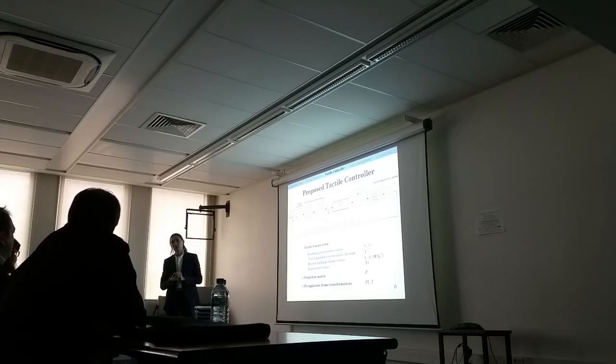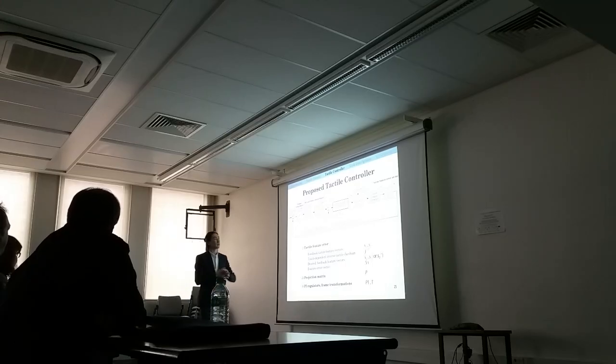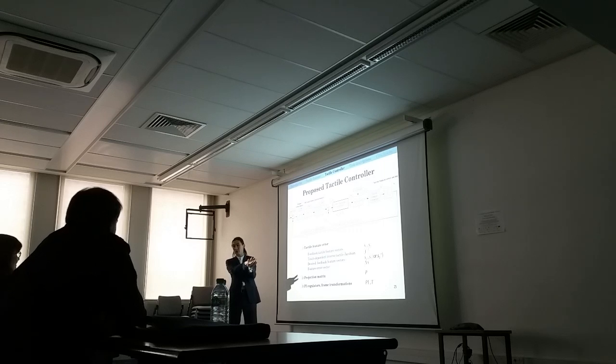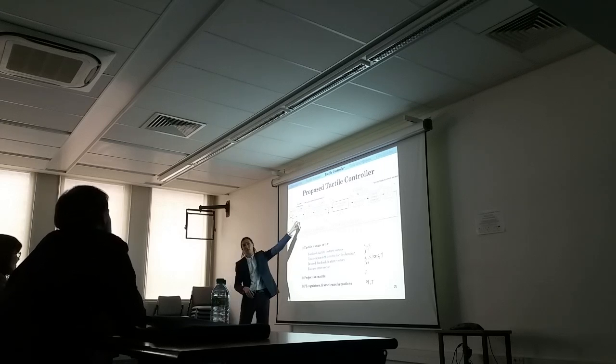Okay, but how do you manage it, because you change the coefficients of this matrix during the task? Yes, in order to start the exploration, as soon as the end effector is, for instance, aligned with some edge, it can start the exploratory movements. So the projection matrix sets this in motion.